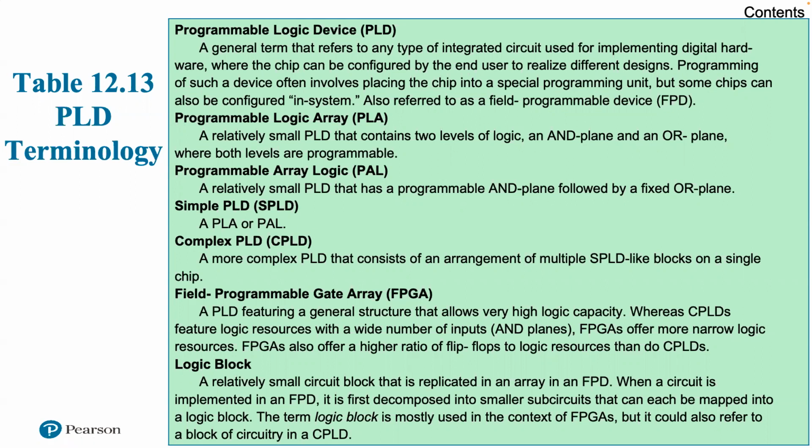As the level of integration provided by integrated circuits increases, other considerations apply. Early integrated circuits using small-scale integration, SSI, provided from 1 to 10 gates on a chip. Each gate is treated independently in the building block approach described so far. To construct a logic function, a number of these chips are laid out on a printed circuit board and the appropriate pin interconnections are made.